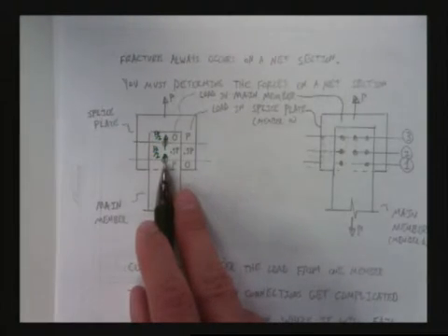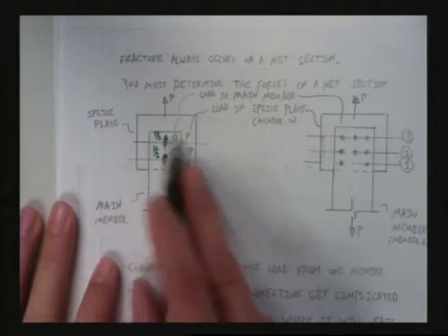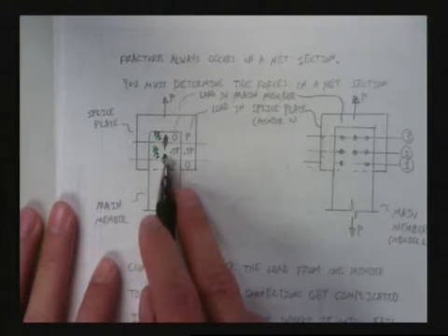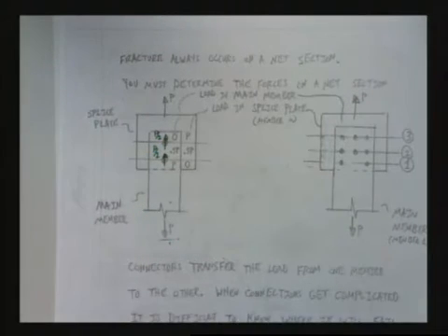And it's going to say, please, I can't take any more, and it's going to ask this other bolt for more help. As long as the system is ductile enough to allow that load transfer to happen, it will, and it'll keep happening until both bolts are at their limit. Then structural resiliency will say both bolts will fail simultaneously. You with me? Great.